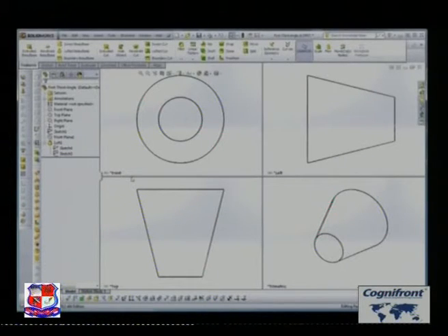Think about this as being your fold line for the first angle projection. Instead of folding that down like we did in the third angle, this gets folded up. So now that becomes consistent with the top view. Instead of the top view being on top, as we would consider the orientation of the piece of paper looking in front of us and on the computer screen, it's actually on the bottom. And then our isometric, bimetric, or trimetric view is over here on the bottom right-hand side. So I hope that helps.